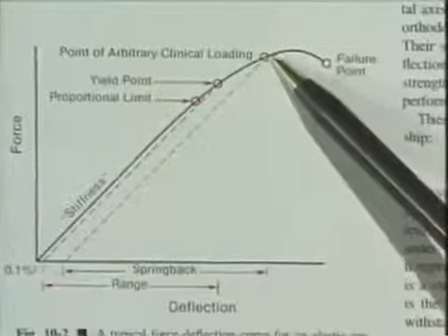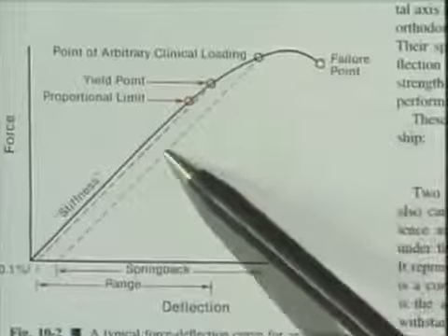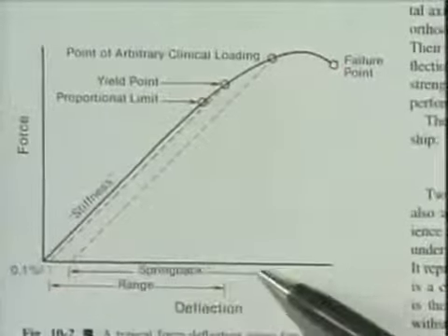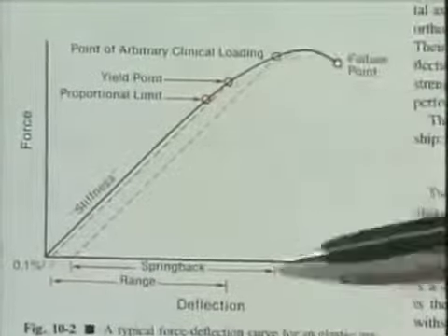If, for instance, Jim McNamara installs a spring and he bends the wire to the point that it's partially permanently deformed, it'll spring back along this line that's parallel with the original one, and you'll end up back at this point here. And so then you have a spring back along the x-axis that's the useful range of the wire from that point of loading back to where it ended up.